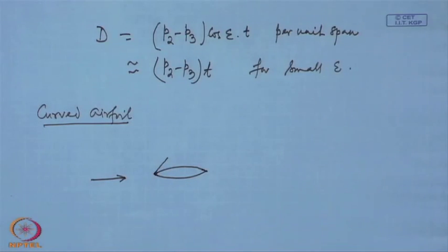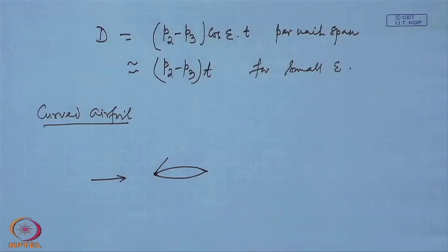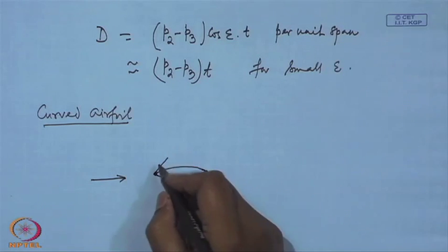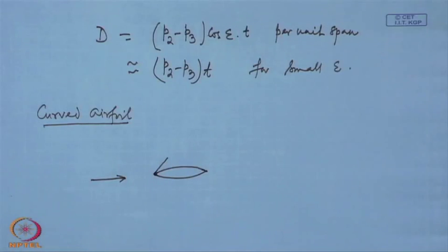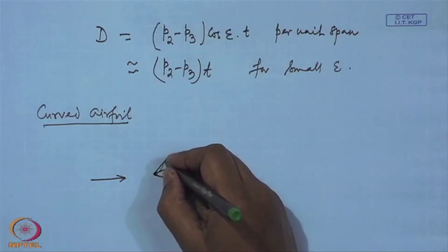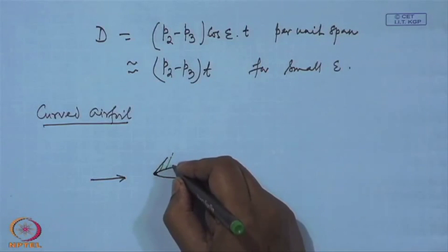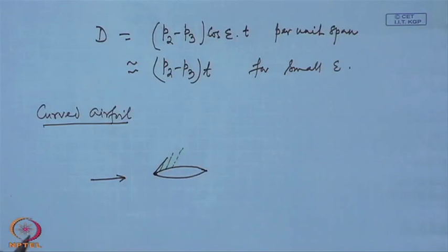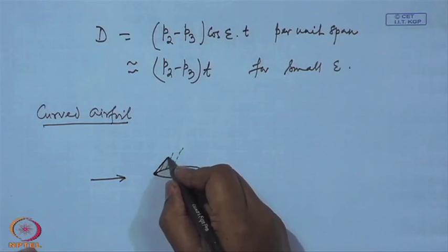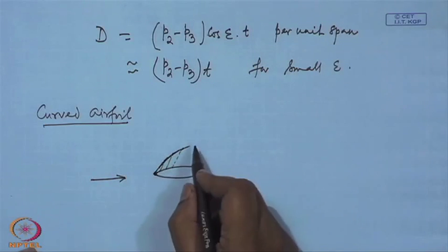However, subsequently there is a continuous expansion along this surface, and these expansions are very close to the shock, and they will interact, and consequently the shock will become curved.